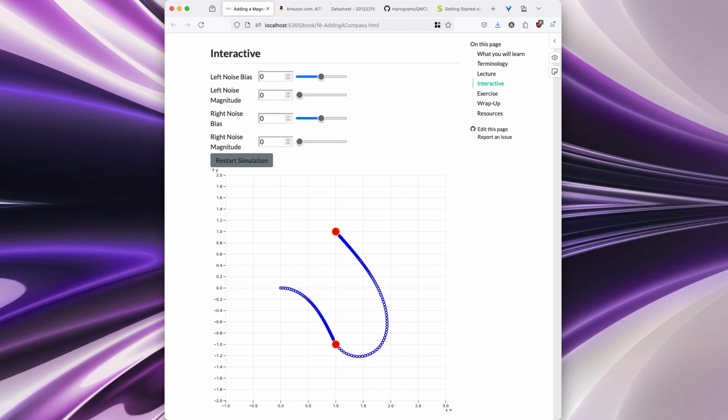That's because the forward kinematics operate using only the wheel encoders as the source of information. And the wheel encoders don't have any knowledge of how the robot's actually moving around in space. They only know how the axle of the motor is turning. So if the wheel slips, the wheel encoders won't register that. If the robot hits a little rough patch in the carpet, maybe the carpet's torn in some spot and it gets bumped off course, the wheel encoders don't register that either. And so that builds up in the form of noise.